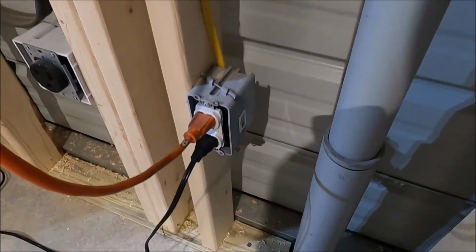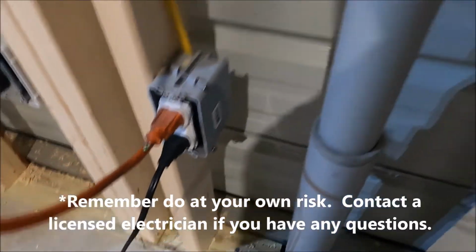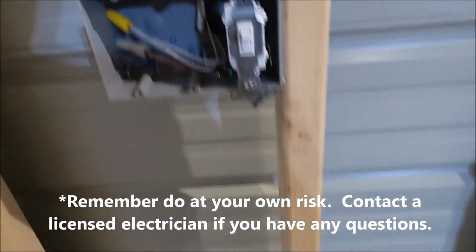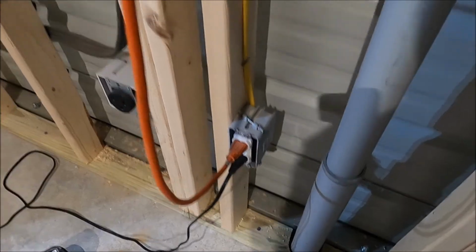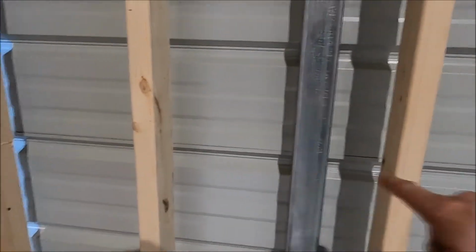Something to always keep in mind, whenever you're doing any type of electrical work, is there are always codes for everything that you do. One of the codes they have is how far outlets should be off from the floor, and how far switch boxes need to be off the floor. I have these 48 inches from the bottom, and the bottom of these outlets is 18 inches. A lot of people in garages will put their outlets 4 feet or whatever. I like mine a little bit lower.